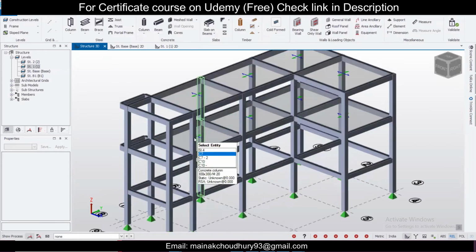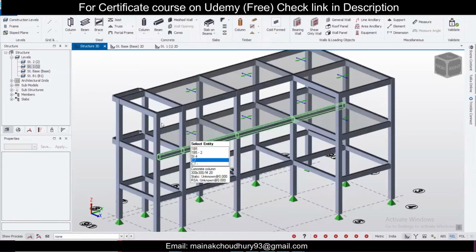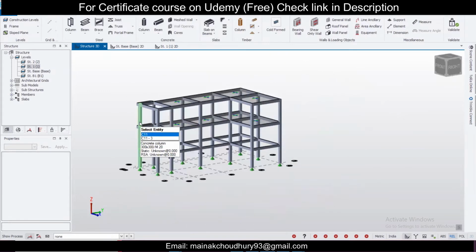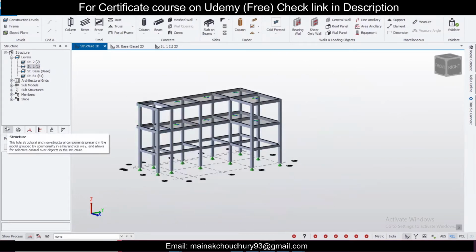Now, the most important thing which we shouldn't forget is the headroom. So for the headroom, just make sure you have a level here. Generally, the headroom heights are taken as maximum. I'm taking a maximum of 9 feet, and 8 feet is also okay for the headroom level. Okay, if we take the maximum of 9 feet, then 9 divided by 3.28 is 2.74.